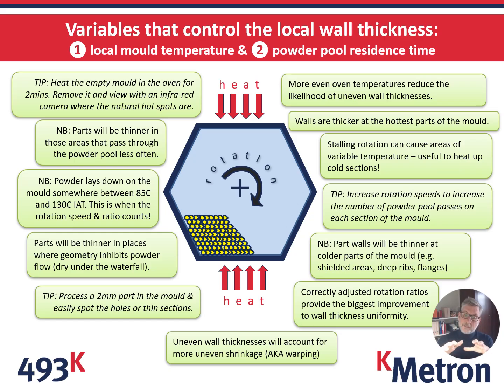Then you will be able to see much more easily the very thin parts of the moulding, perhaps where there is no polyethylene at all. So if you're having problems, use a smaller shot weight to get a clearer picture of how the wall thickness is varying.